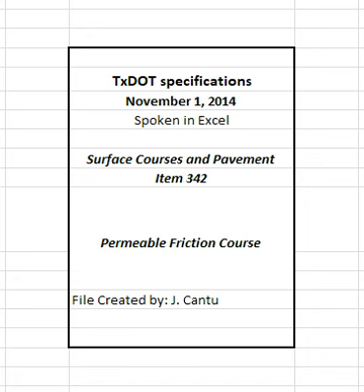4.7.1.2 When not using a thermal imaging system, place mixture when the roadway surface temperature is at or above 70 degrees Fahrenheit unless otherwise approved or as shown on the plans. Measure the roadway surface temperature with a handheld thermal camera or infrared thermometer. The engineer may allow mixture placement to begin before the roadway surface reaches the required temperature if conditions are such that the roadway surface will reach the required temperature within 2 HR of beginning placement operations.